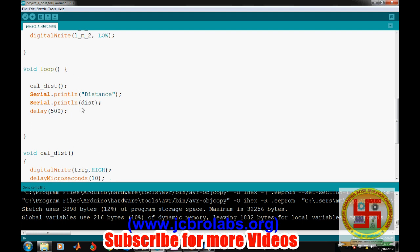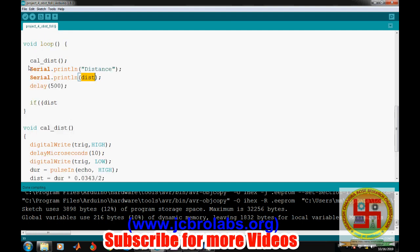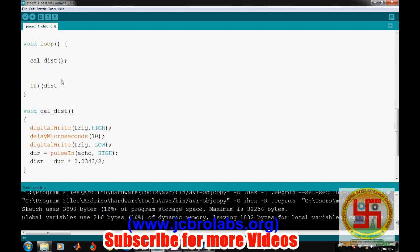So our logic is very simple. If the distance measured by the ultrasonic is in the range of 9 to 15 centimeter, it should stop. Okay, so we'll check it. Let's say if distance, this variable has been updated with the distance because it's a global variable, so we can access this particular variable within the code anywhere, right?